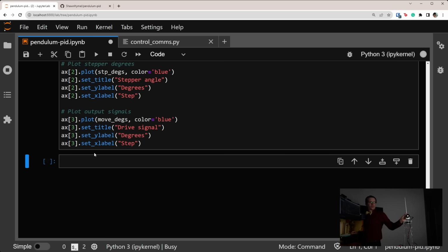Let's move exponentially here. So rather than, say, having this, let's go to 0.01 and see what happens. Oh, wow, that's really good, actually. That's almost where we want it. Still looks like it's oscillating some. So let's stop that. Go take a look at our plot. Yeah, there's still some oscillations here. You can see it hitting up too high in the beginning, and then it's oscillating a bit. Let's see if we can bring that down just a little bit.